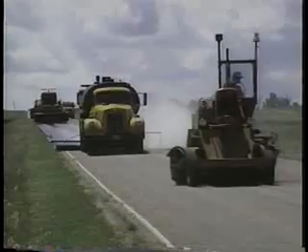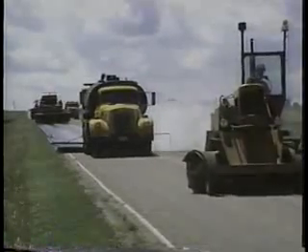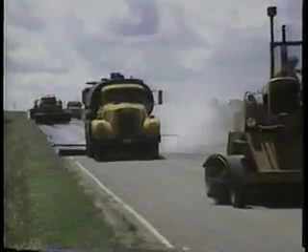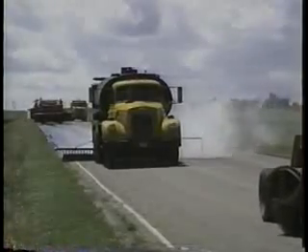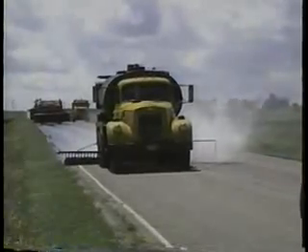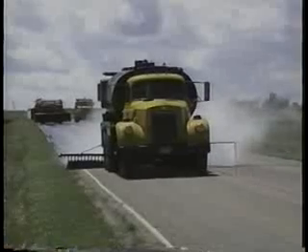You should also be aware that high wind can greatly affect the binder application, so don't apply the oil if the wind speed is excessive. Of course, nothing causes more problems than moisture, so the operation should not begin at all if rain is likely.